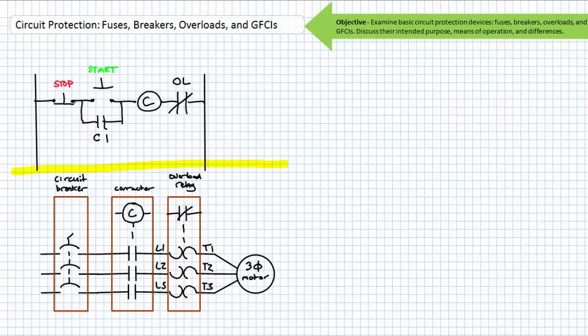The time period before an automatic reset allows the overload element to cool. Due to the cumulative nature of heat, overloads that have been triggered once will trigger earlier if subjected to the same overload. Repeated overloads are a clear sign the motor is undersized for the task.